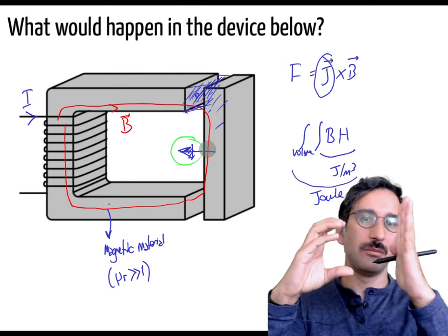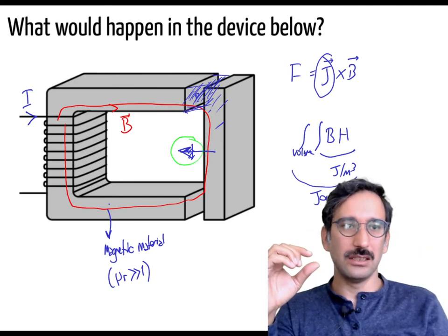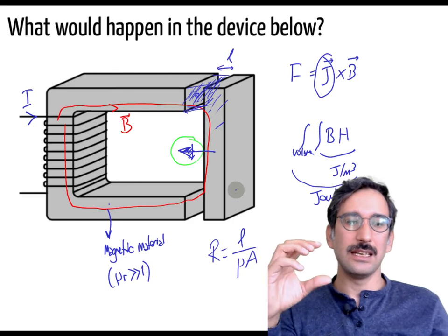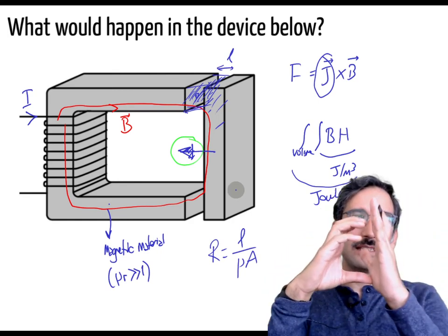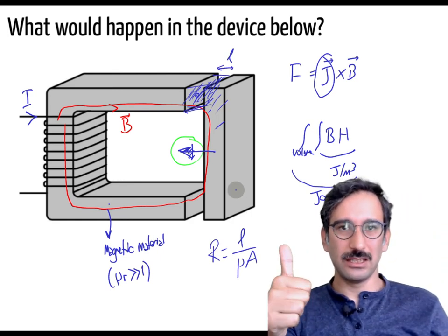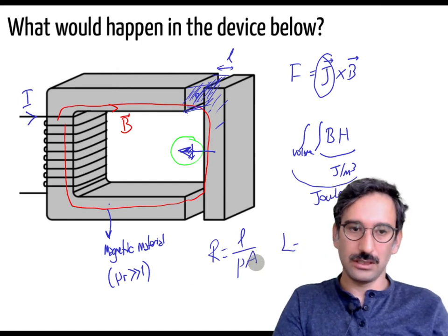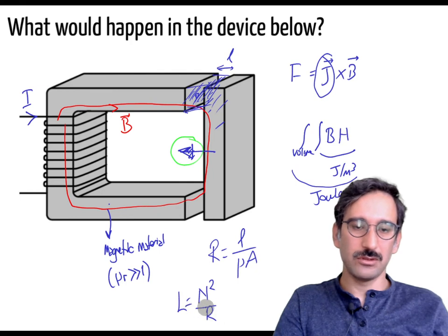that coil, because remember, the reluctance is proportional to the length of that one. As you reduce the length, the reluctance will get smaller, and the inductance, let me put it here, overlap. So L is equal to N squared divided by reluctance, so they are inversely proportional.